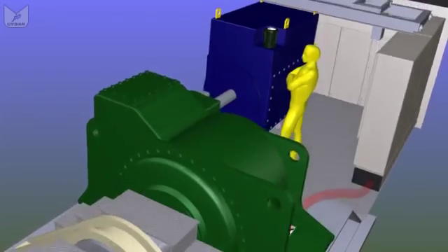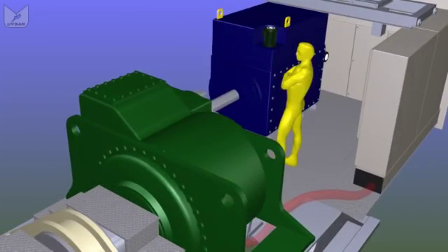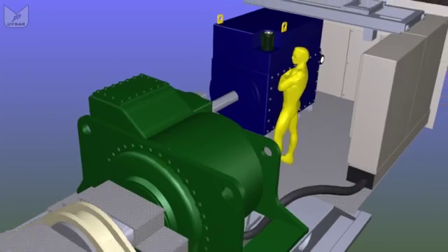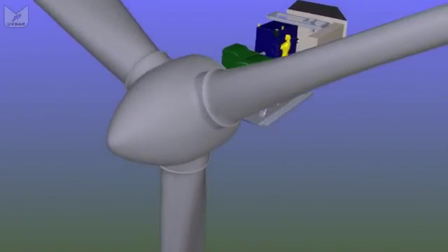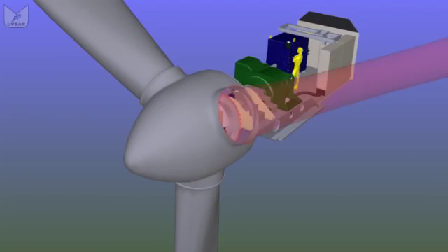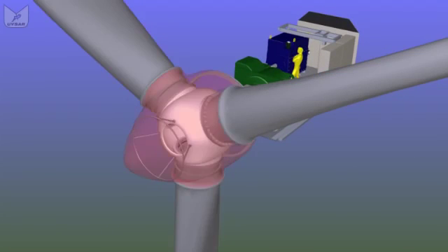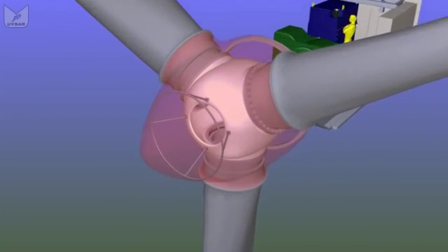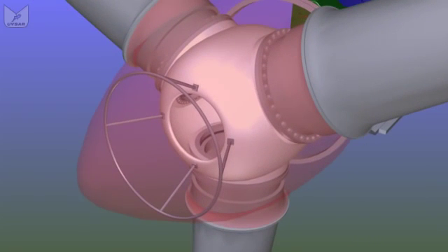And that, as an overview, is pretty much all there is to it. The only thing left to talk about are the blades, obviously, which actually do the work. We still have 3 of them. They still pitch, in other words, they twist on themselves to line up with the wind. And you access the hub through the gap between this fiberglass cowl and the cast hub.